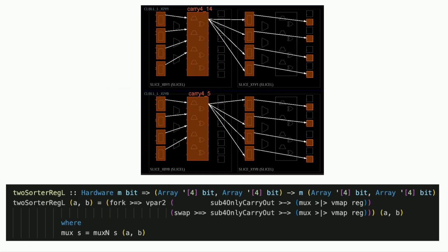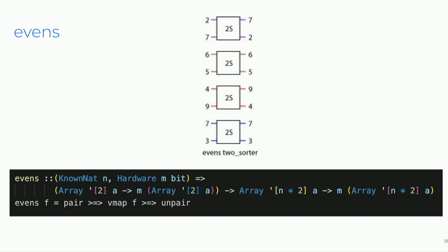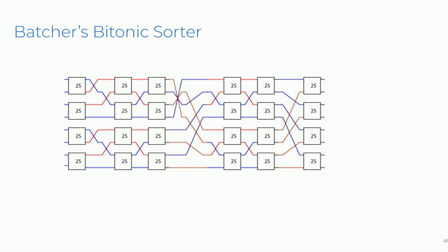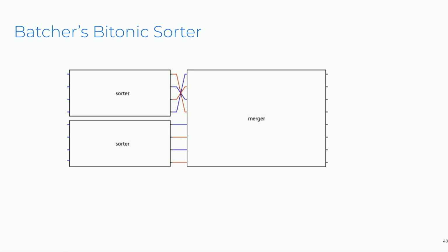And what this is, so this is a sorter, which is a network sorter. This one takes 1, 2, 3, 4, 5, 6, 8 values, and each node is a 2 sorter. It will sort 2 values, and then if you push left to right through its network, at the output you'll have a sorted version of the inputs. And it's built with a butterfly merger, which is what's on the right, and 2 smaller sorters. So you can sort of see that structure there.